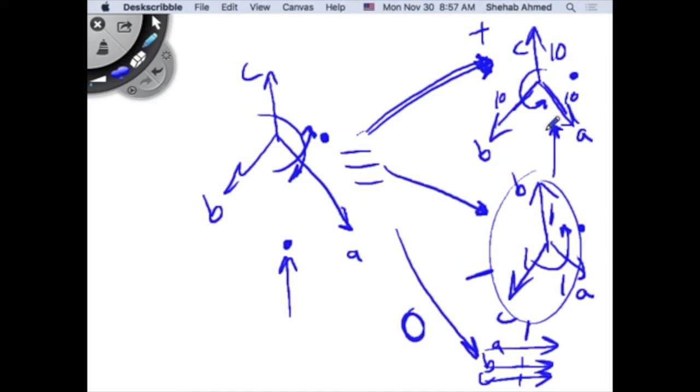So you had the positive sequence current contributing to torque. Then you put a supply in the opposite direction on the motor, trying to flip the direction, right? So what did that do? That supply, superposition, right? It's the source, and you have an RL load. Same, superposition, current will flow, so you have to sum up the current. That current will be additional current in the winding, and it's going to generate torque in the opposite direction of the positive sequence, meaning it will reduce torque on the output shaft. So you've reduced torque, and you have more current in the machine, right? So you're heating up the machine, basically.